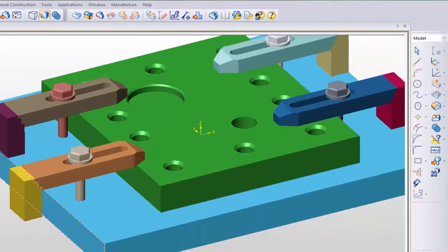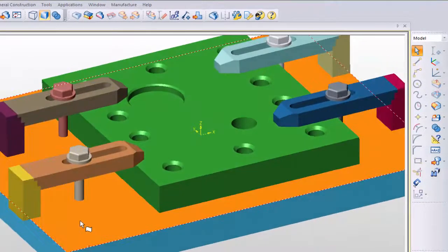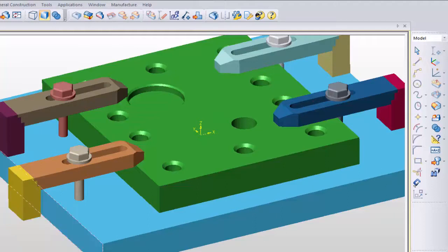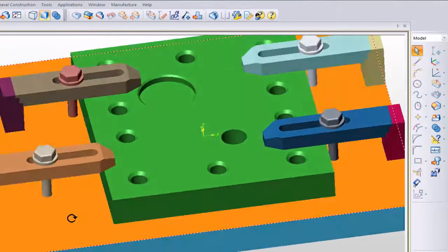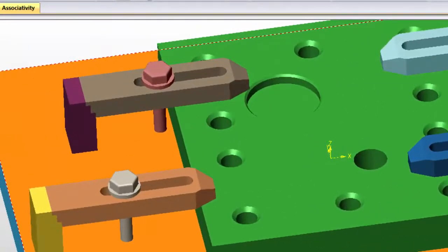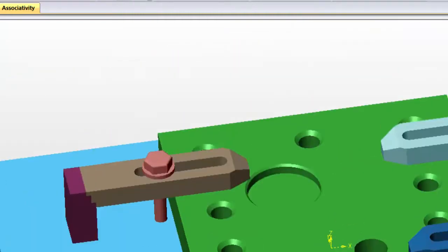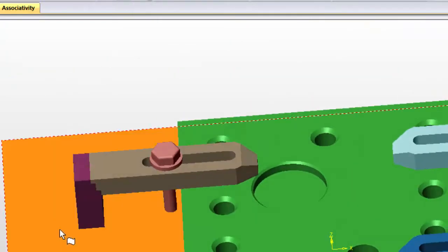Okay, it's not quite enough, so let's do a bit more. We can just click on the process and make it 35, and that clamp is clear. So now I know that I've got to make this plate bigger. You could say, well, use a smaller clamp, but those are all options we've got. I could cut this clamp down in this modeling system and sort it out that way.